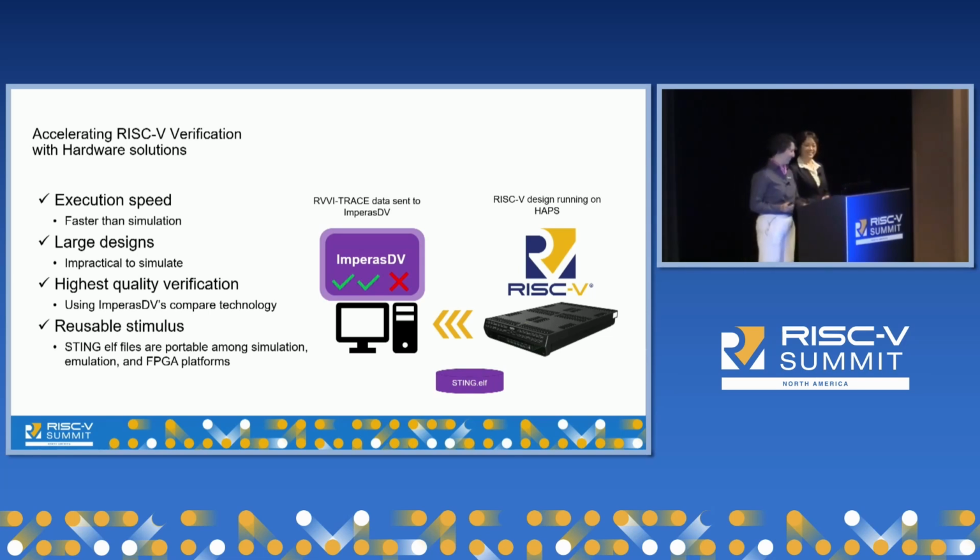Another dynamic approach to verifying large designs involves the use of an FPGA or a prototyping platform. In this scenario, the synthesized design executes the test at hardware speed, while trace data, which contains changes in architectural state, is dumped to a file or database and then streamed to a connected host machine. The data can then be checked for correctness by comparing the state against a reference model. In this environment, longer and more intensive test programs can be run, including real software such as booting Linux.